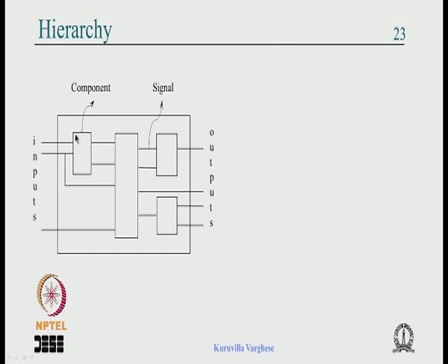and this wire or the signal connecting them should be of standard logic. So we have to declare the distinct components we are using for the interconnection in the architecture declaration region, all of them, and we also have to, you see this signal, this is not part of the input or output. So we have to declare that signal, it is called signal which has no direction, because a signal connects one output to one or two inputs normally, unless you use a tri-state gate.